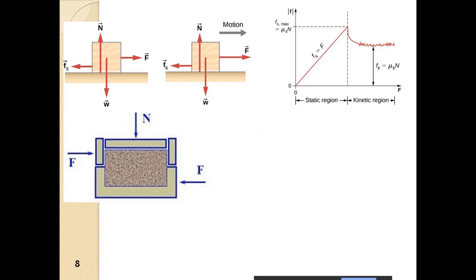As we have discussed, we have this soil mass and this mass on top, and this bottom mass. As we increase the normal forces, suppose we give one N1 and we will require F1. First we plot N1 and then we plot F1.